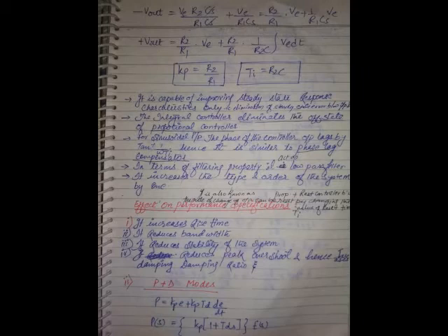Fourth point. The sinusoidal input. The phase of the controller output lags by tan inverse 1 by omega Ti.